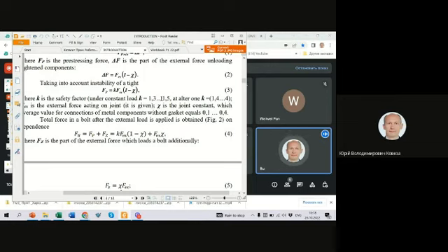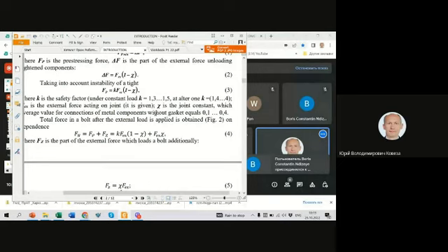We can't find it right now because to calculate joint constant, we should know these parameters: stiffnesses of joint and bolt or flexibility. That's why we need to use recommended values.